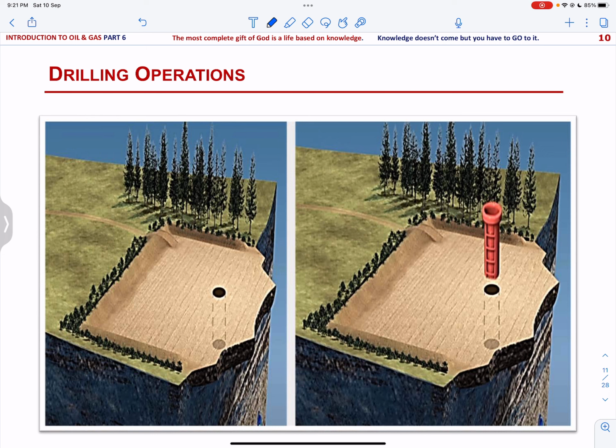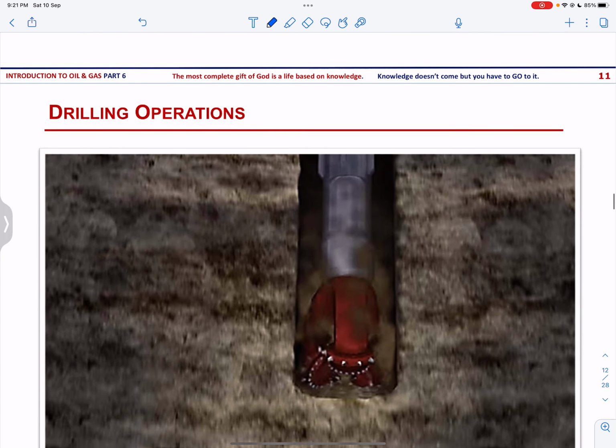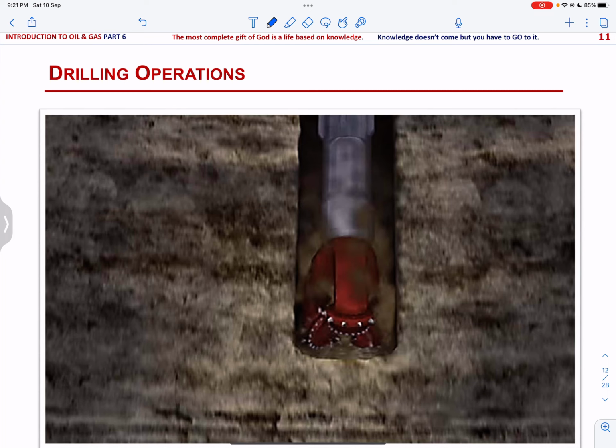Initially, and prior to moving in the drill rig, a large diameter hole is drilled for the first 50 to 80 feet. Conductor casing is then cemented into place, stabilizing the ground around the drilling rig and well head, and isolating the well from most private water wells. Air drilling is done until the hole is advanced to an average of 100 to 200 feet below the base of the freshwater zone, which provides added protection to the freshwater zone.